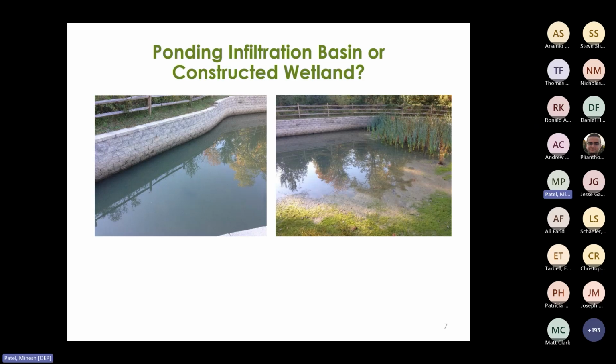Now, based on the presence of the wetland vegetation and the standing water, the right type of maintenance was obviously not performed and it became what you see now. At this point, the basin would need repairs or it may even need a retrofit.